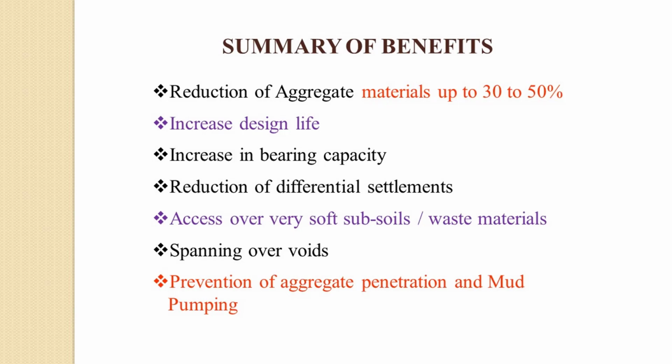But as I said, the pavement consists of two parts. One is the foundation, the other is the BT, the unpaved road portion and the BT. Now, for a new road it is okay; I can place a geosynthetic material at the subgrade-subbase interface. But if the road is already constructed, it has exceeded design life or it was poorly constructed, whatever the reason it has failed, what can I do? That is an existing road. That is where the asphaltic reinforcement comes into effect.